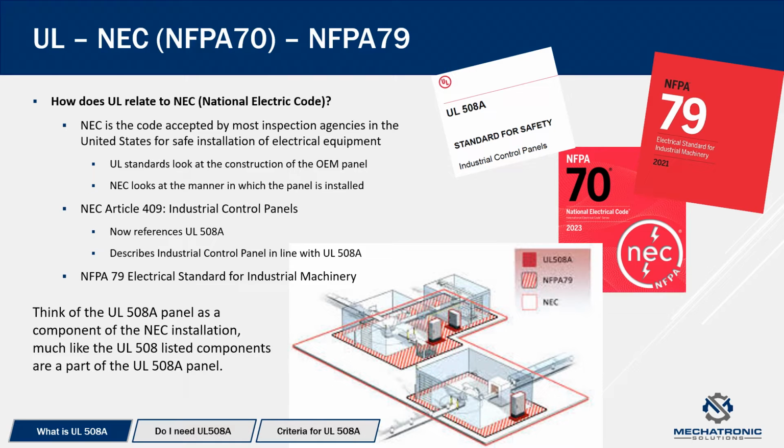So that's going to be more akin to the service installations, that electrical service that gets installed. The UL standard looks at the construction of the panel, where the NEC is going to look at the manner in which that panel is installed.